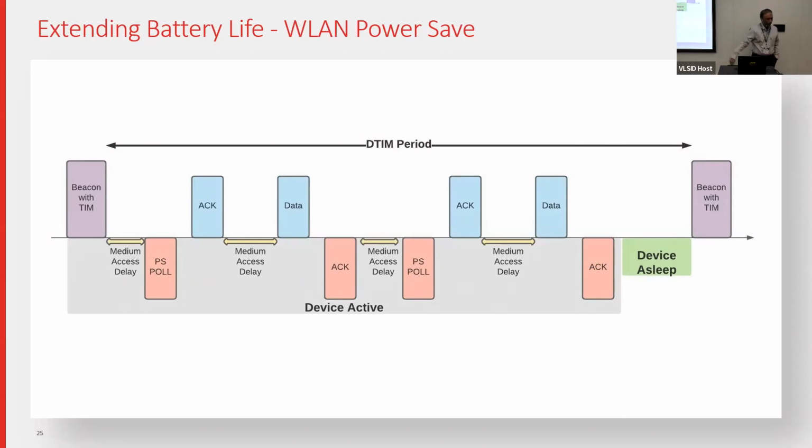Similarly, 20 other IoT devices in the room also wake up at the same time. Then they all transmit at the same time. And then all the transmissions go bad, no ACKs. Then each of them has a random timer to decide when to transmit again.